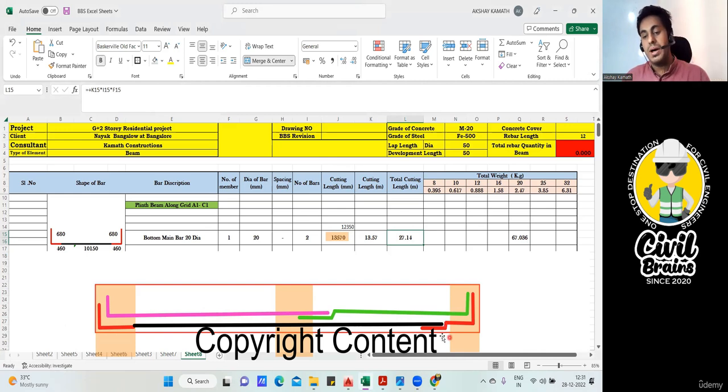Now you'll bring one more bar where you'll give a small bend, that is the lap. So this lap length will be 57 times the diameter of the bar. It will be bent in this way. It won't go across like this. A slight bend, something like this, will happen, and then this L will happen. You getting my point? This is what we do practically on the site. Or you can even follow the second method.